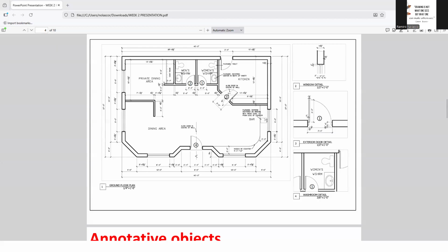But that's for alternate units. Primary units, suppress. Suppress 0 feet. Maybe if I say no. Suppress 0 inches. Maybe say no there. Okay. There. So, can I do it from the dim styles right away?